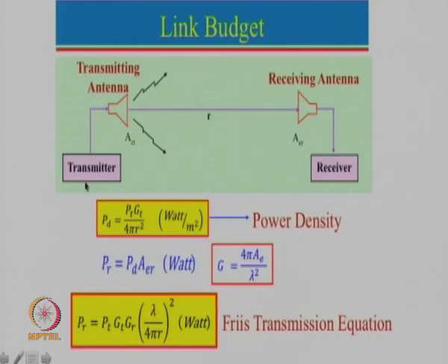The transmitter power again depends upon the range we want to cover and also the receiver sensitivity. Just to give you an example, we all use, let us say, a mobile phone. The receiver sensitivity of a mobile phone is as good as minus 100 dBm, and for some mobile phones it works even at minus 108 to minus 110 dBm. In fact, the majority of mobile phones show full strength at minus 70 dBm.